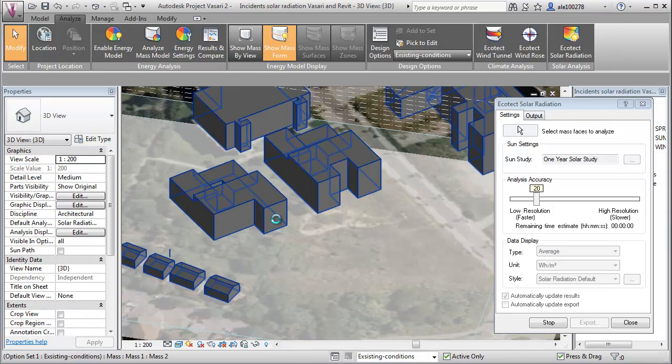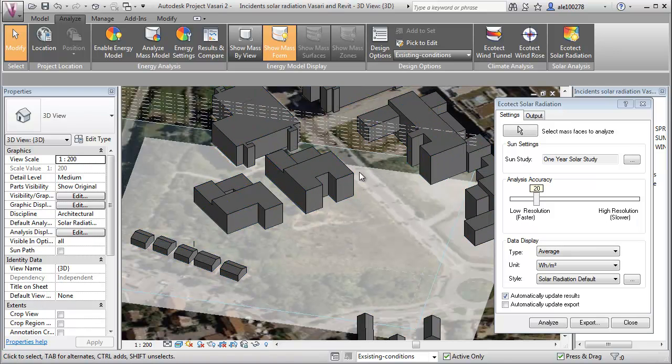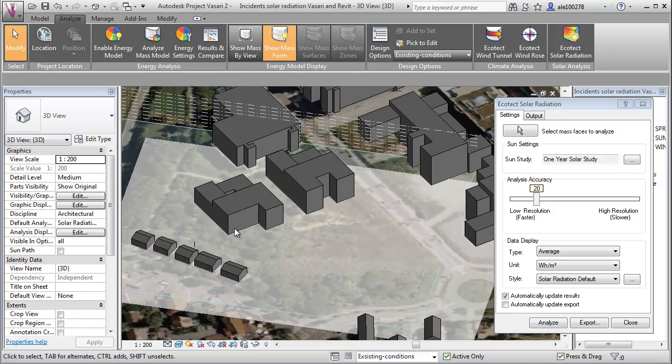What I often begin with is, I know from this project that it was a demand that we shouldn't make too much impact on these three facades here and on these facades here. So really to measure how much heat they're getting as incident solar radiation on the existing conditions, and then being able to use that for comparing different design solutions is one of the things. And then of course when we begin our development, which I will get back to in a minute, is how we can use solar radiation to optimize our geometry and the interior design conditions of our spaces.